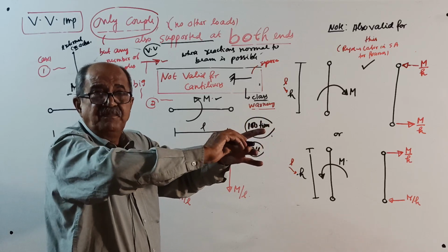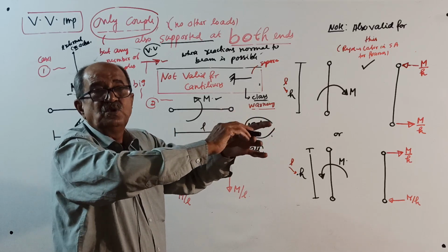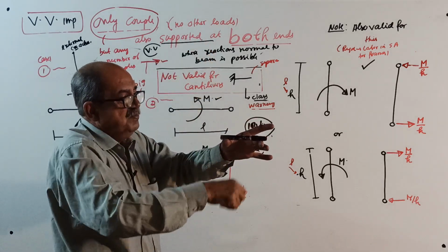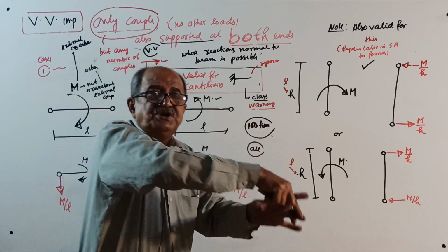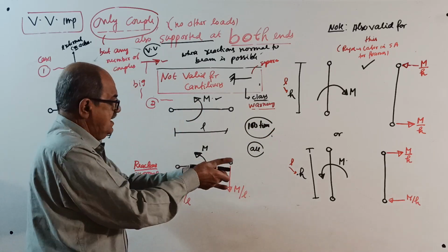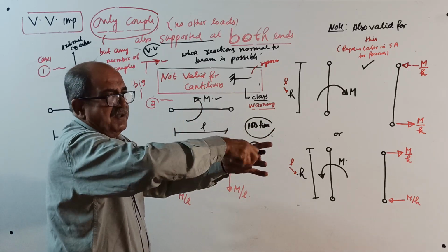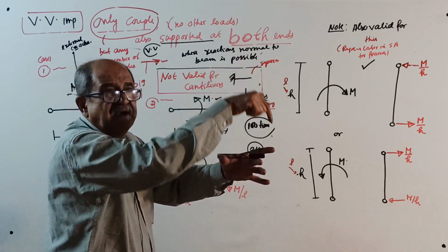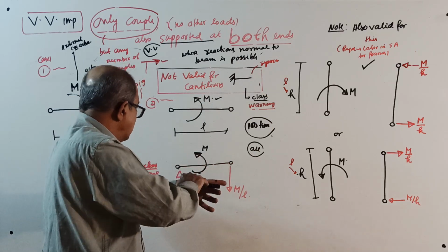That is lifted because of action. So reaction should prevent it. It should bring it down. See, down. That side, it will try to push. So reaction is up. Here, if you apply an anti-clockwise couple, that side will get lifted. So you require reaction down. Here, it will press up.